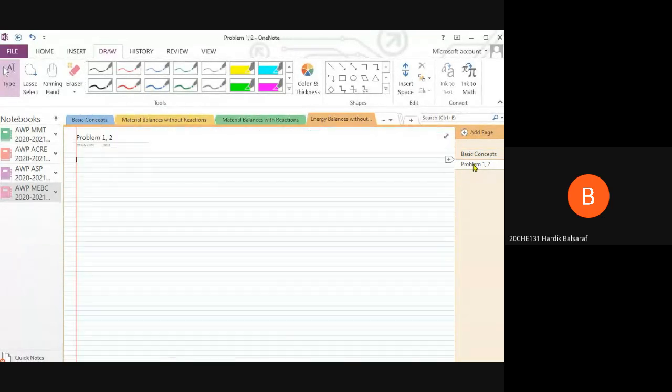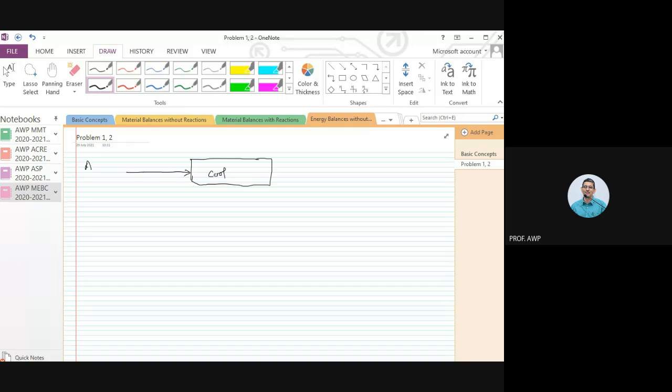Yes, sir. Okay, so here is the next problem. We have been doing all kinds of condensation problems, right? Where we cool the air. So imagine that we have ambient air. Let's say total pressure is constant, 760 mm Hg. So we might want to use psychrometric charts. Ambient air temperature is 45 degrees centigrade, percent RH is say 80%. We cool this air so that the temperature becomes 20 degrees centigrade.